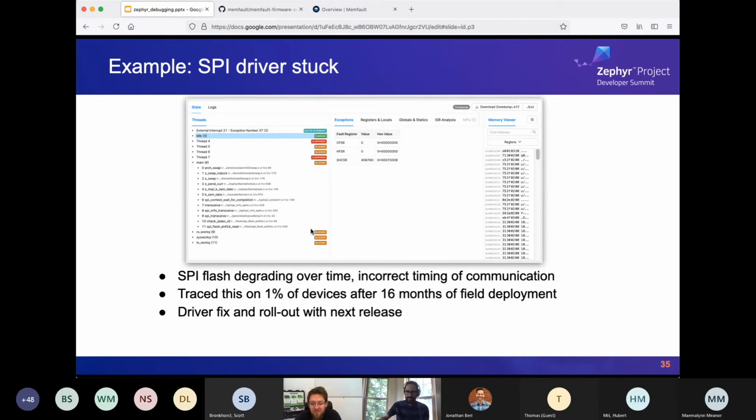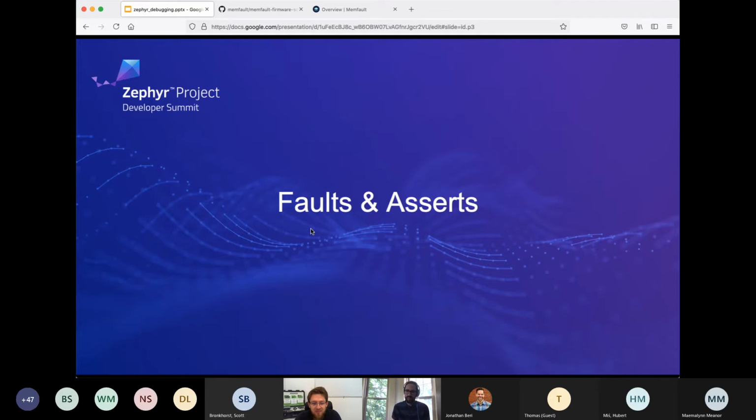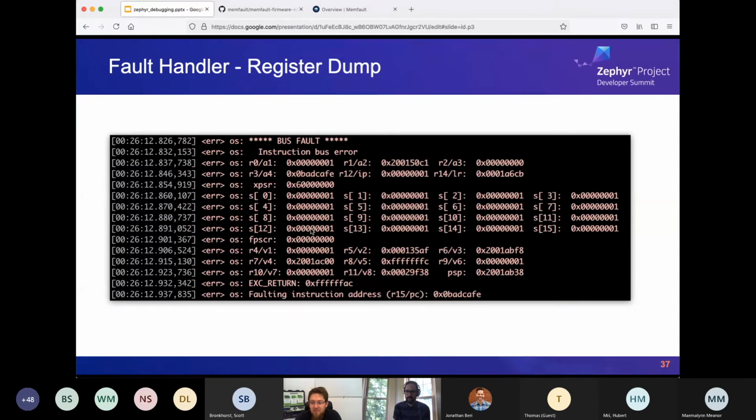Yeah, so the watchdog, as I alluded to, is kicking off the Zephyr fault handler, via when we call an assert. If you've ever done some local debug or built some features of your own, you've probably seen a screen like this on your computer about register state when a fault has taken place on the platform. These can be due to asserts or accessing bad memory or dividing by zero or using a peripheral in the wrong way. What I want to talk about here is how Memfault stitches into this path and what we were able to collect that you can look at.